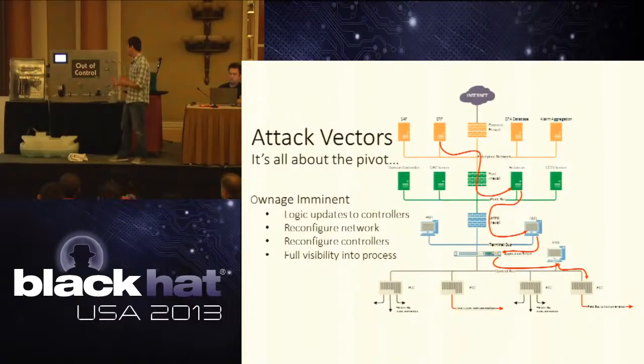And why that's important is because in the olden days, you had to take a PLC offline, modify the logic, and then bring them back up. But you don't have to do that anymore. The reason is that plants require almost no downtime. You need your wellhead to be up all the time. So you're able to modify logic in real time without ever bringing down the process, which is awesome for a hacker, right? Because nobody actually knows that any change has ever been made. The process keeps going on normally, or how you want it to go, but you never have to actually take it down.